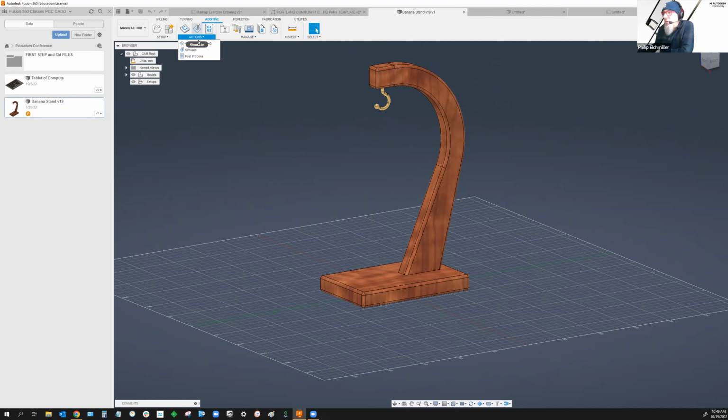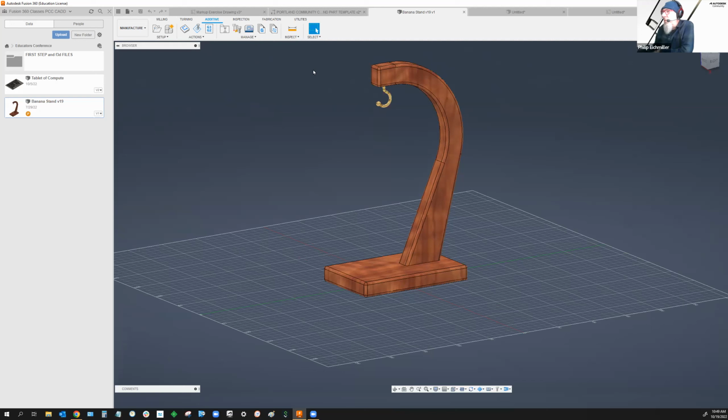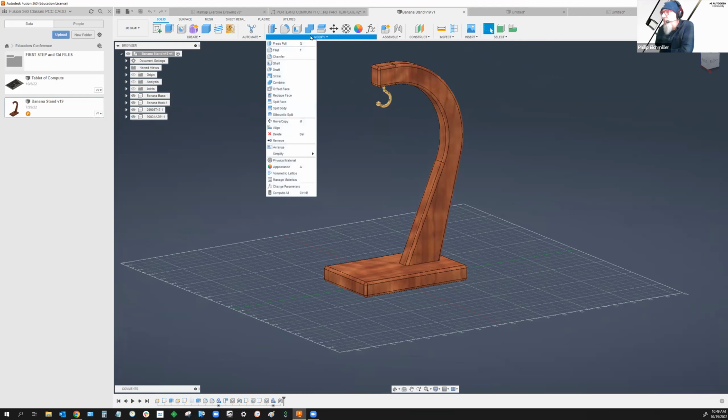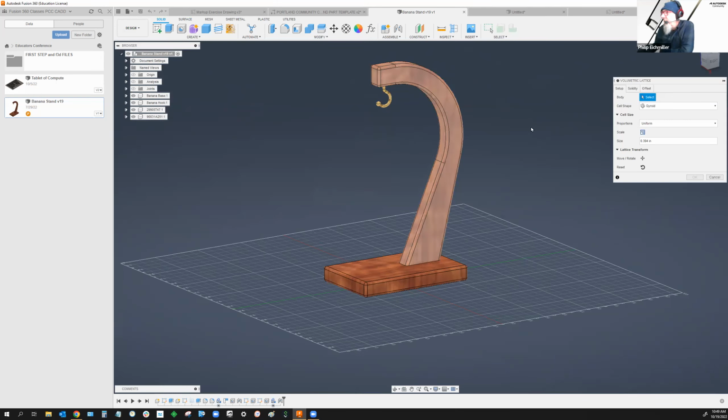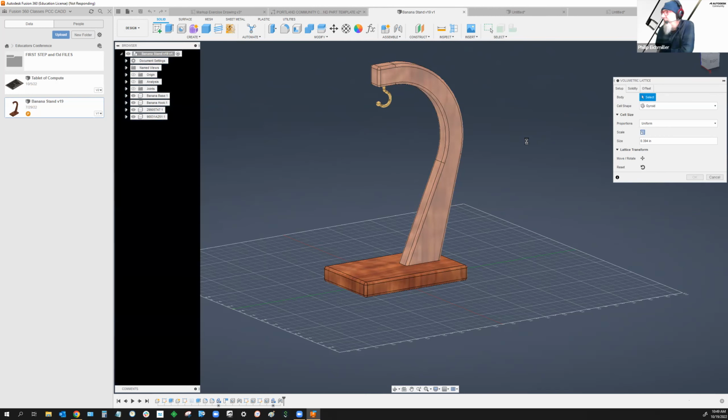You're creating toolpaths in G code, and you can trim and edit those things, so you can be very, very specific about it. If you want to have full control over what's inside of your models, you can use the volumetric lattice, and you can set this up so that you can define all of your own infill.